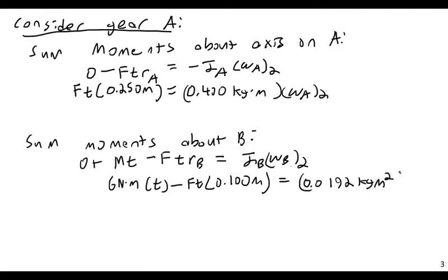And then we can say omega B2, the final angular velocity. Now, if you go and calculate the angular velocity, we do actually know the final angular velocity. 600 RPM, if you remember from the problem statement, is the angular velocity of gear B. And that means that omega B, I want to be consistent and say omega B2, is 600 RPM.